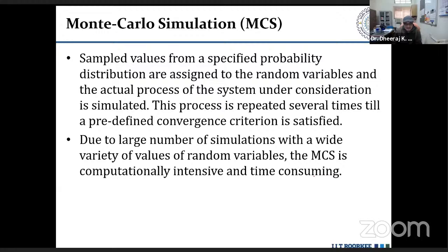For example, suppose we have solar photovoltaic in our distribution system and we have to compute the losses. And let us say we are considering a time period of 1 day. And we are assuming that for a given hour, the solar radiation is constant. But still we need 24 values of solar radiation, or at least 12 values in which we have sunshine.